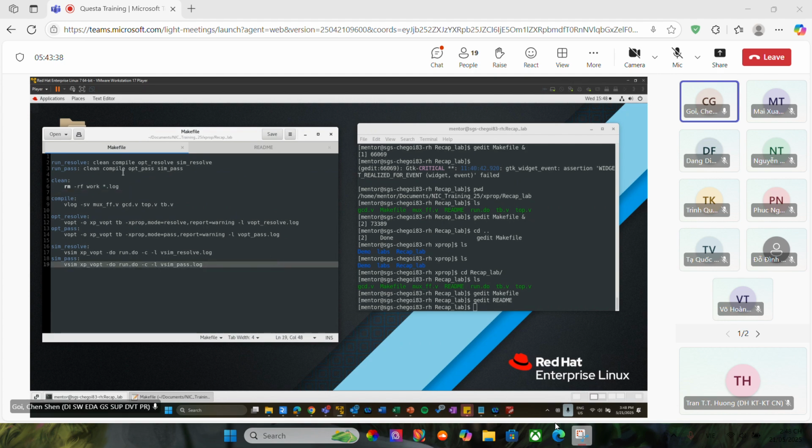Let's see from here. We have run resolve, and run resolve has a dependency on clean, compile, optimize, and simulation. Let's look at each of the commands first. The compile command is very straightforward vlog. We just specify SystemVerilog and all of the Verilog files.